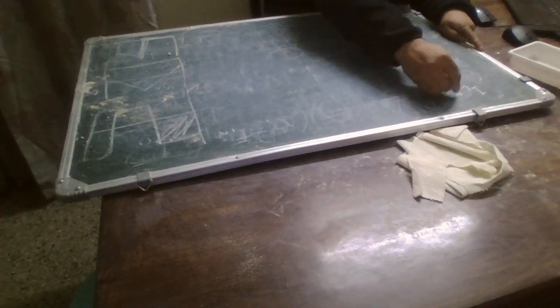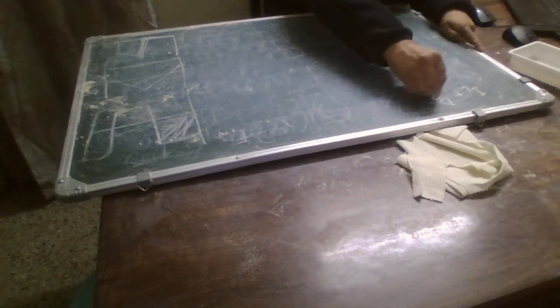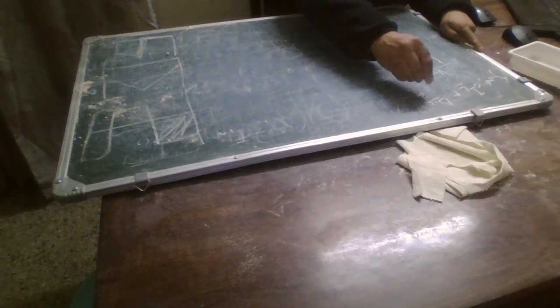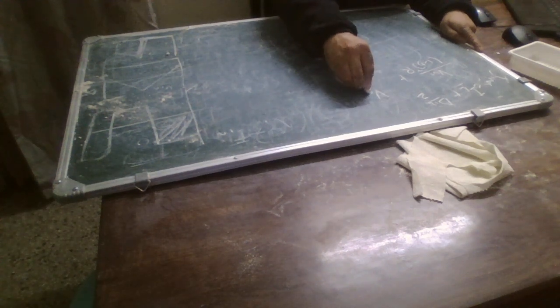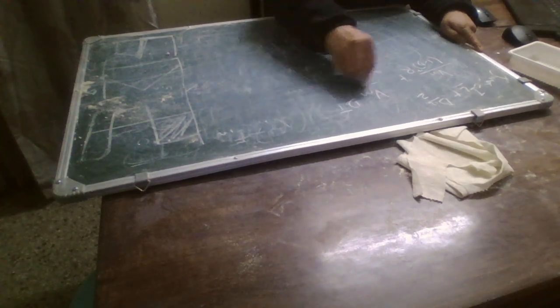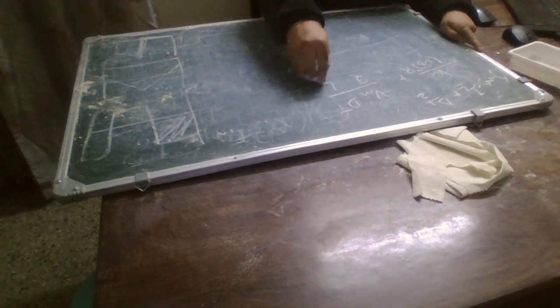Putting in the value of IL I have just got, I max is V input upon 1 minus D square R plus V input DT upon 2L, because I have already got it from di by dt.